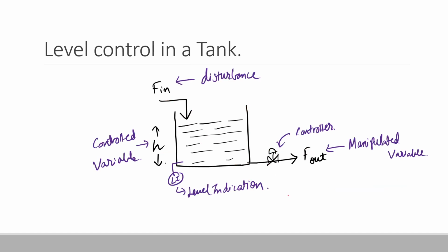Now, in terms of control philosophy, since we are not able to control the flow inlet, that is not in our hands, we call this term a disturbance. Whatever parameters or variables we can't directly control, we treat as disturbances.